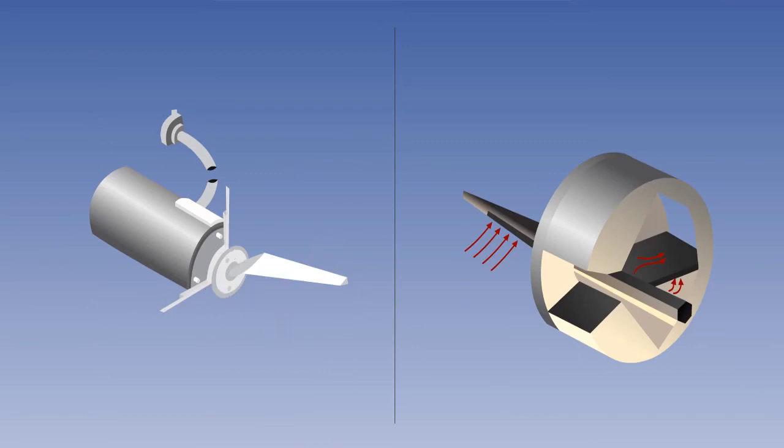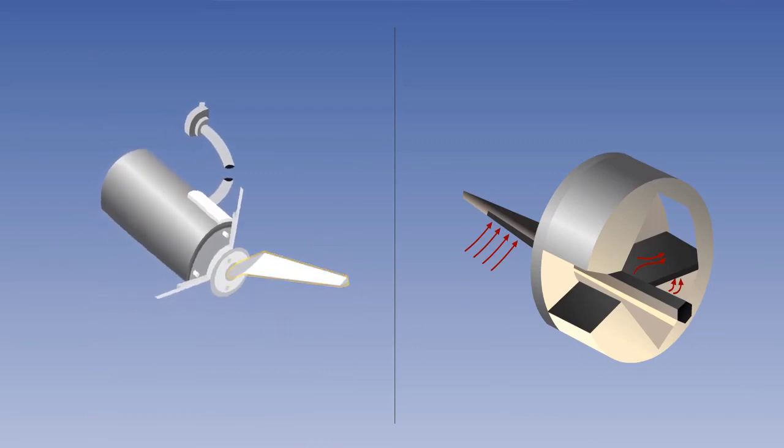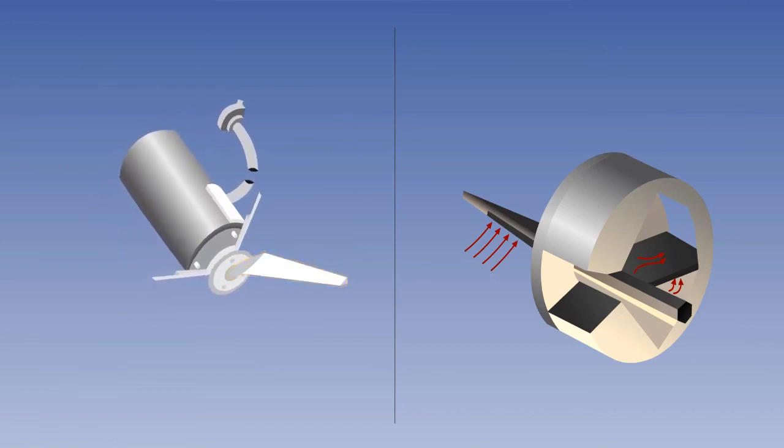The vane detector is a counterbalanced aerodynamic vane, which positions the rotor of a synchro, which is used to measure the subsequent angle. The conical probe protrudes from the side of the aircraft into the airflow.